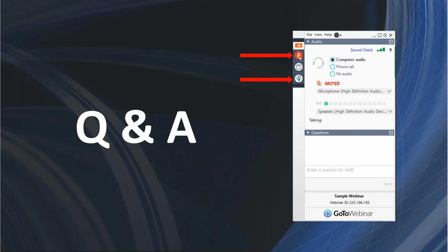Because the optimum filling sequence is different for different people. I could put a large part in front of 10 people and have them all give me their opinion on where knit lines need to be and where the gates need to be, and I'm going to get 10 different answers. That's why we simulate a lot of different things, because there are a lot of trade-offs. If we have knit lines here, it's going to drive pressure up, or if we move a knit line over there, it's going to change the filling pattern or the fiber orientation pattern, which is going to affect the warpage. So there are all these trade-offs.